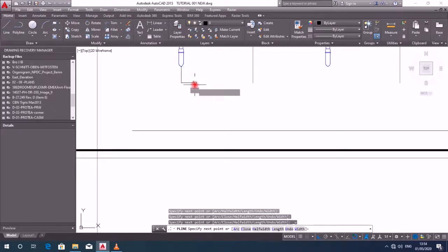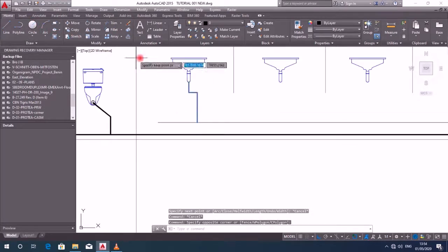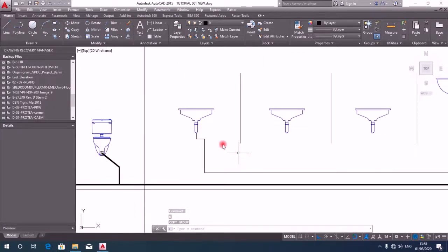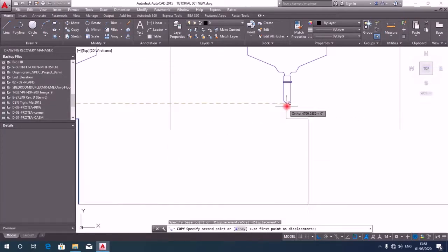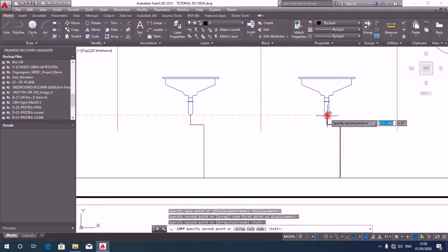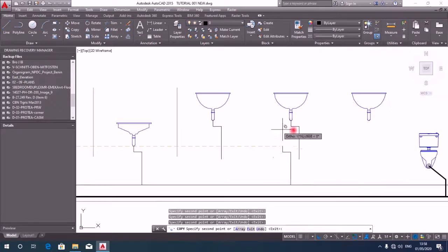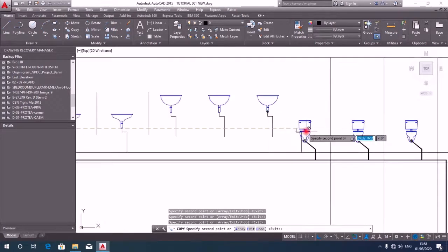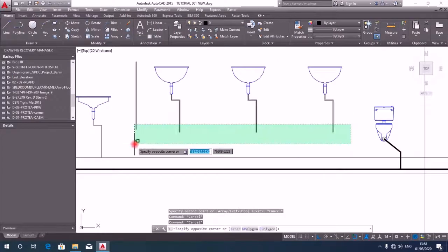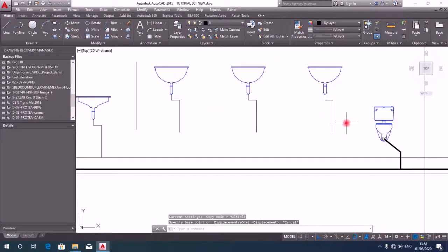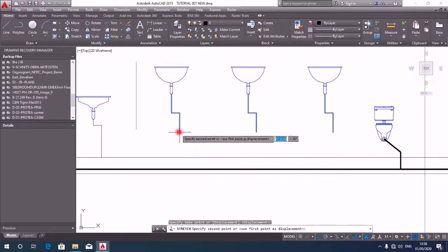How do we want this to be? Okay, so just put it like that. So we copy this to other places where we need it. It's all showing the 50 mm sanitary pipes. Okay, for urinal and then WHB.